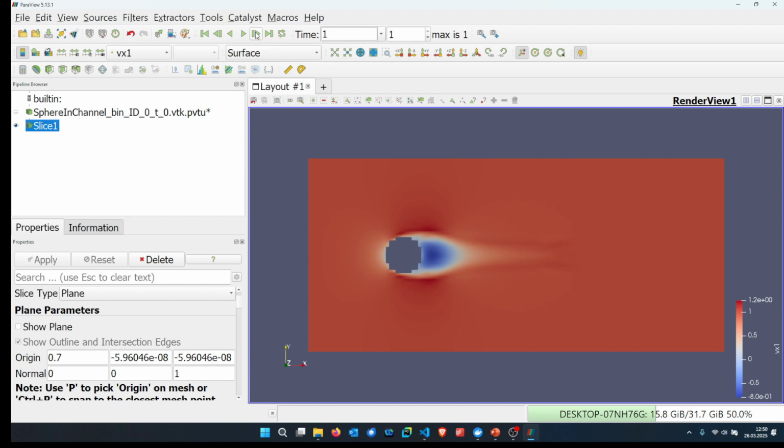I thought it's crashing. In the standard solver, if you try to simulate an atmospheric boundary layer without any accounting of the small under-resolved turbulence, then in the standard CFD code we will also see that the flow would just not feel that there's a wall down there. It would just flow like a very fast flow, there's simply not enough friction. So like a slip boundary condition. Yeah. Zero viscosity, it may go to an Euler solution. Yeah, basically it's like that.